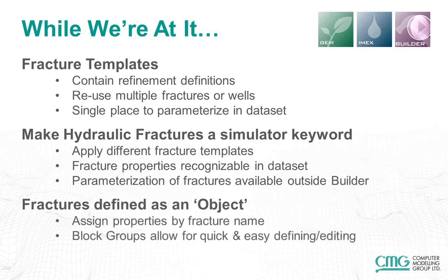So for example, if we wanted to have different relative permeability curves for our matrix and for our hydraulic fractures, we can now refer to the fracture by name and specify one set of relative permeabilities for the matrix and one set of relative permeabilities for the fracture. It can also be used for other things such as initial fluid initialization.